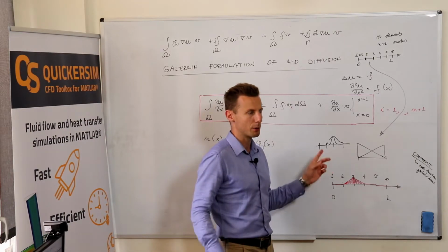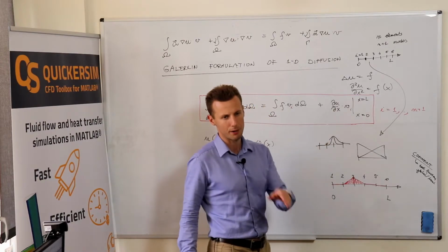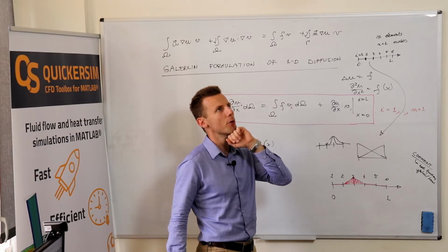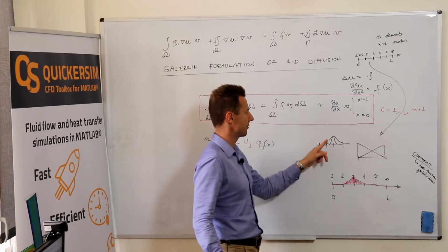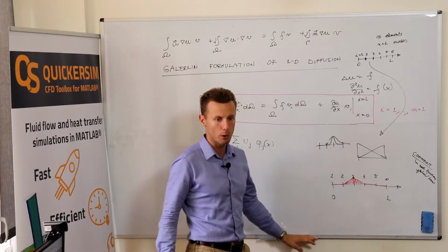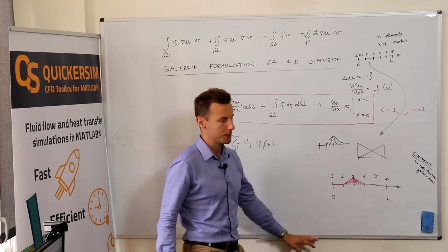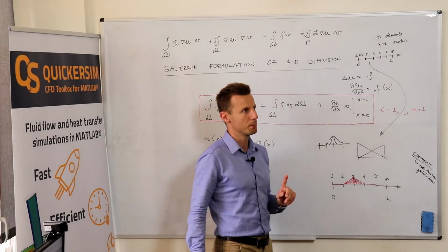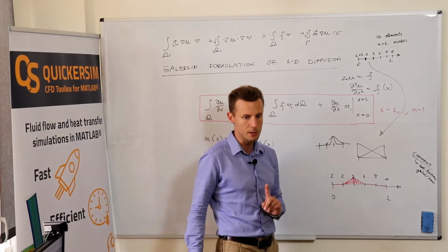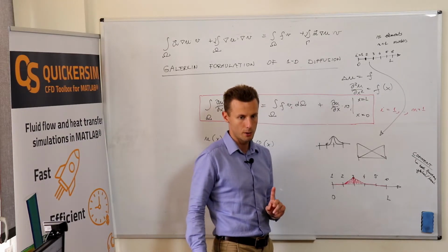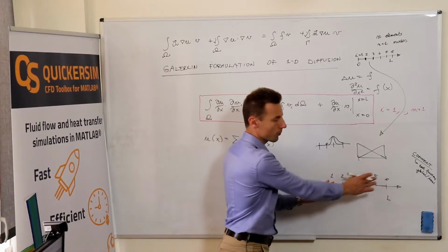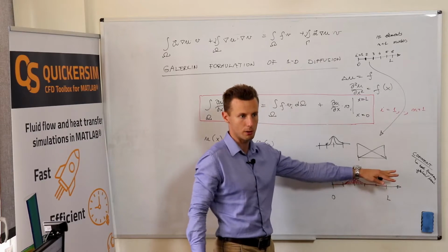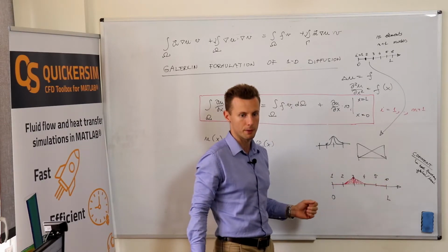But that's one side of it. The theoretical problem is that I cannot show the proof immediately, although it's not difficult. But one of the requirements for the shape functions is that they should be a partition of unity, which means that adding all the shape functions together needs to sum up to a global field of 1 everywhere.